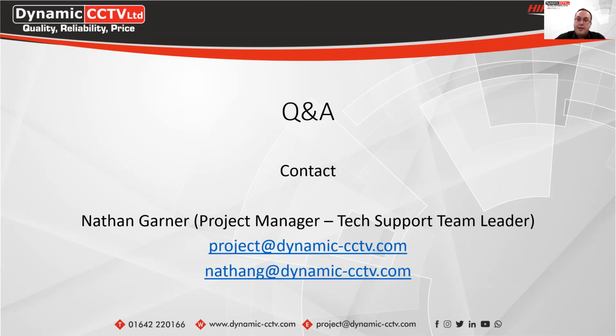Jason has asked if it's possible to interface face recognition, etc., into an existing access control system, for example, Paxton. So there is a way to actually link Paxton access control with the HikCentral solution. It's done by using a middleware piece of software from Hikvision called Optimus for that, which can link the two systems together and synchronize users per HikCentral and the actual Paxton access control system from Hikvision.